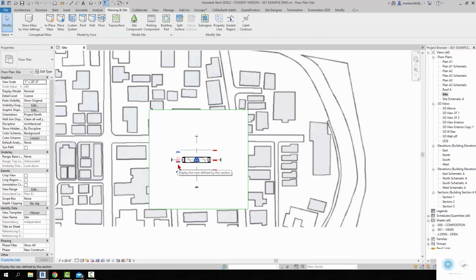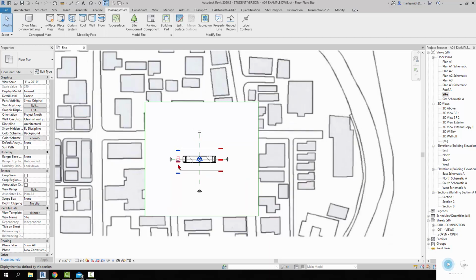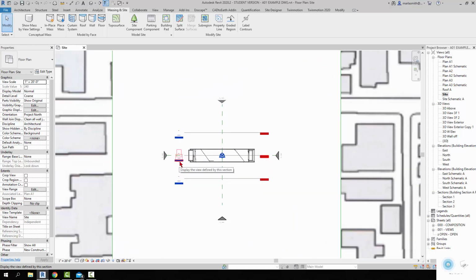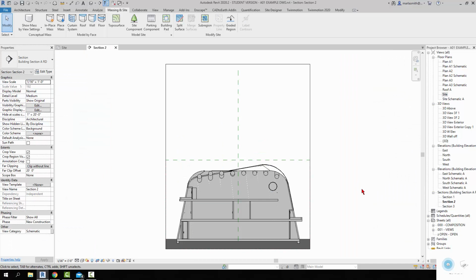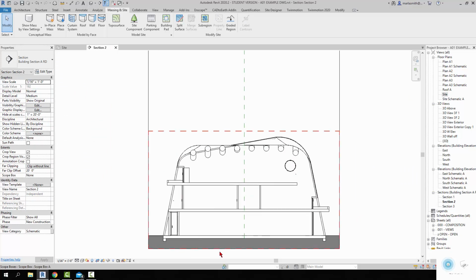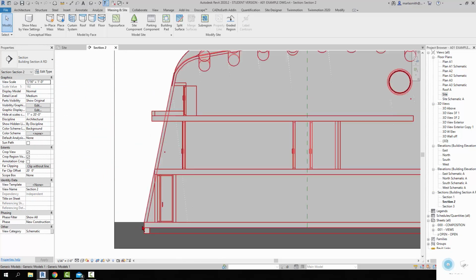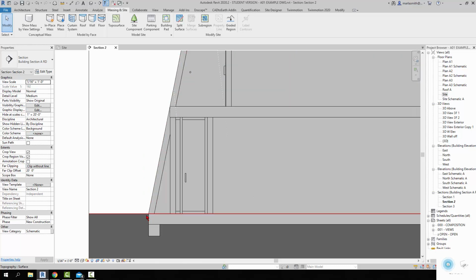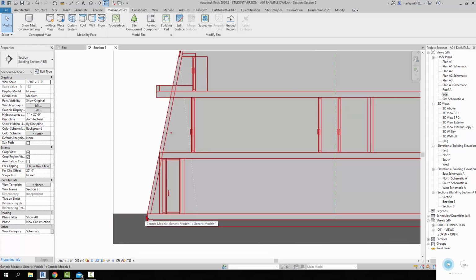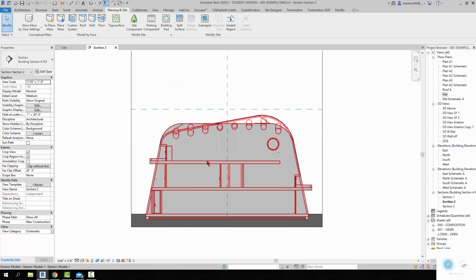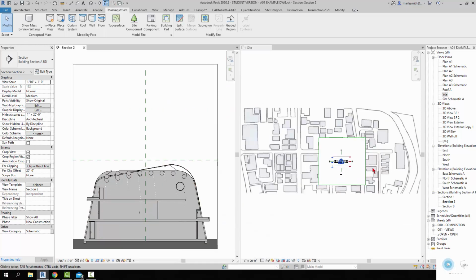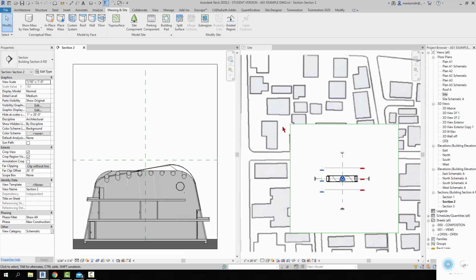So if we go to our section view here, I'm going to double click on the section head, right? We look at this section view, you've got this topography sitting right here, and it's actually at the finished floor. So we'd like it to maybe drop a little bit more, maybe 4 inches, 3 inches at least, probably 6 minimum if you're actually building it so you're not getting flooding. But we'll go ahead and drop it maybe 4 inches. So I'm just going to WTZA, and I'm going to zoom in on this topography over here.